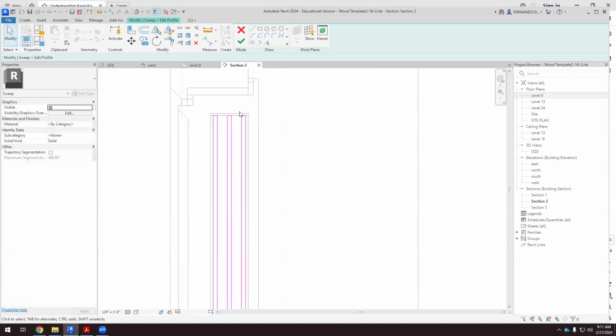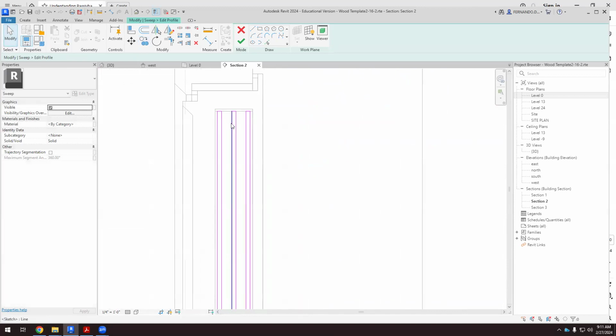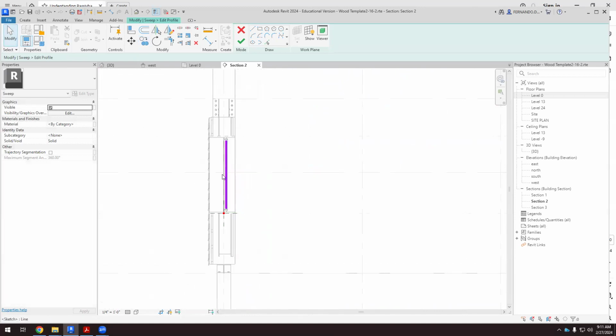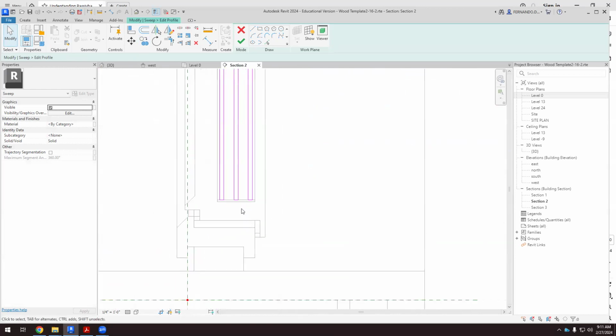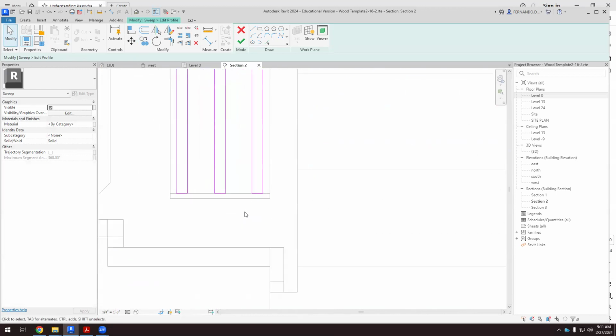Okay, so I have created these 3 rectangles, so those are the 3 glass panes, the triple glazing, and they are in this cavity, but there is always a gap between the glass and the frame itself. So it's not just filling these cavities, we always need a gap between the glass and the frame.